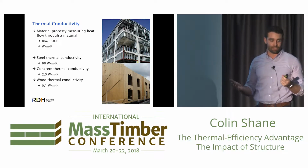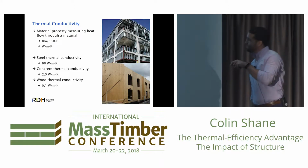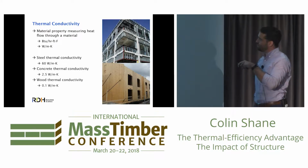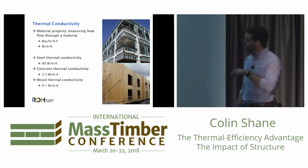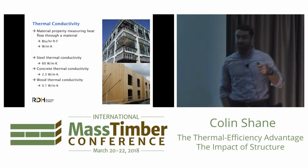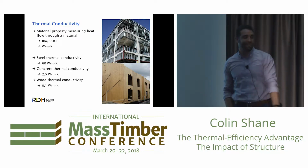Steel is a really good conductor of heat. Wood is a reasonable insulator. Material properties, whether we talk about IP or SI units, round numbers here: steel has a thermal conductivity of approximately 60 in SI units. Wood, by comparison, is 600 times less than that.